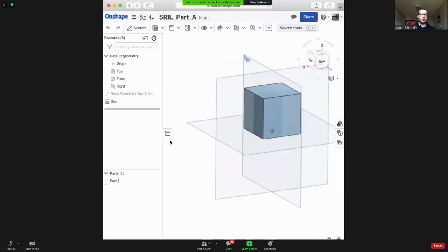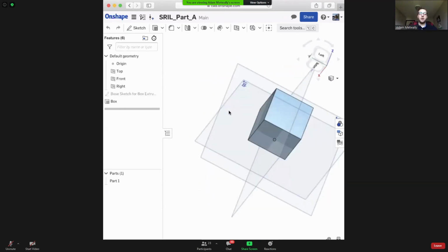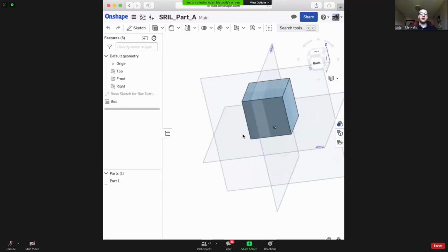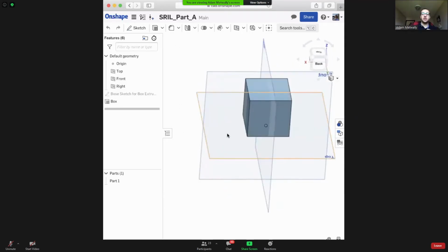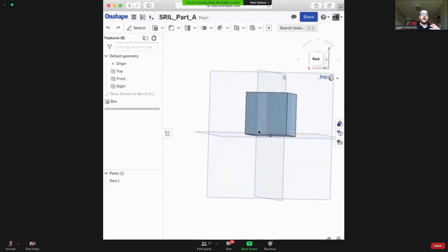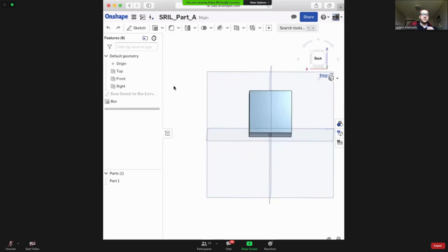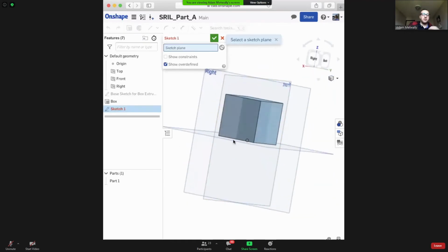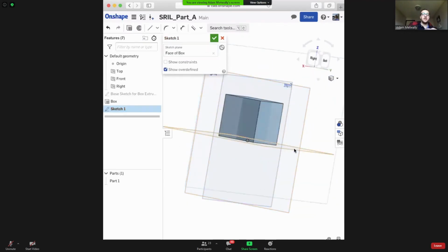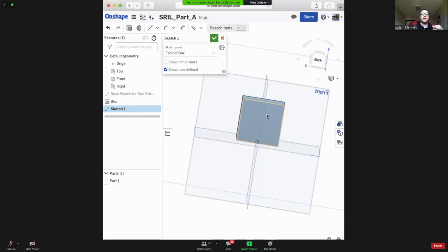Okay, so going back to parts, pretty much what I wanted to illustrate with this example is how things are done in CAD. It generally looks something like that. You're going to create a sketch and you're going to extrude or cut from that sketch. And then you're going to build more sketches. So say you wanted to put a box or a triangle on top of this box, you could then sketch on the surface of here, and you get the picture.